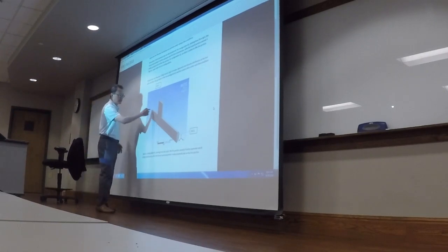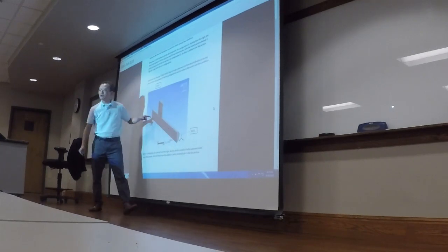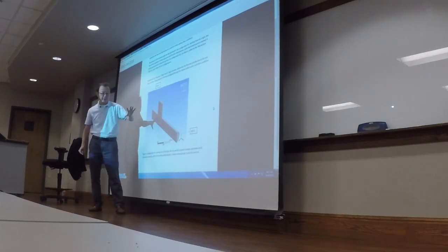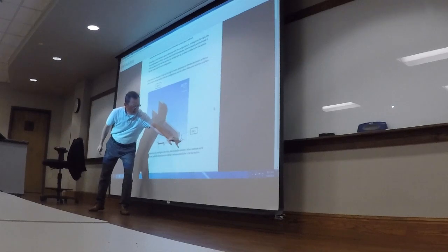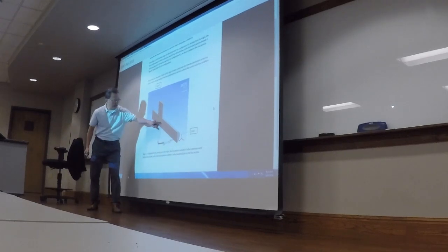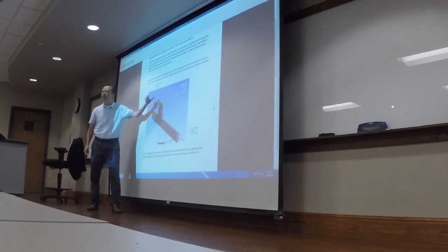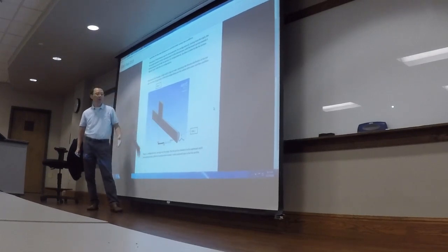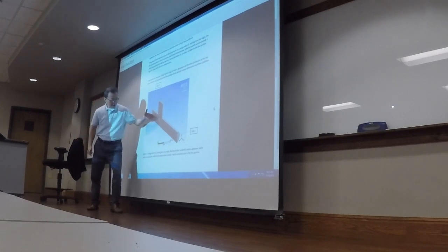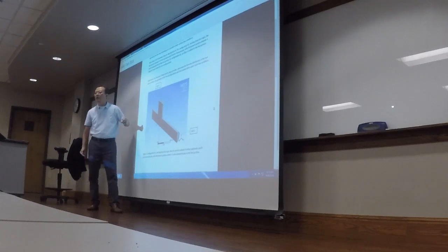Then let's create the semicircle and close that, extrude that for 12 inches. Then on the XZ plane, let's create another semicircle, close that, and extrude that for 4 inches. That's how we get this line portion and branch portion.